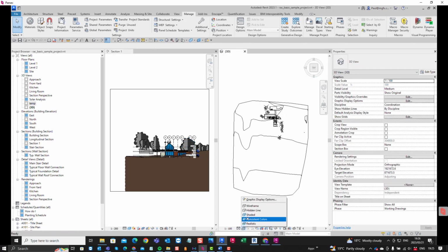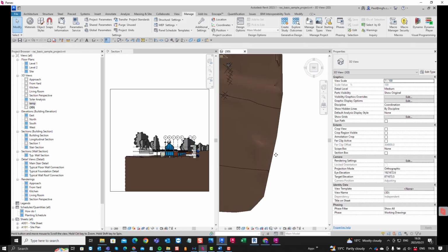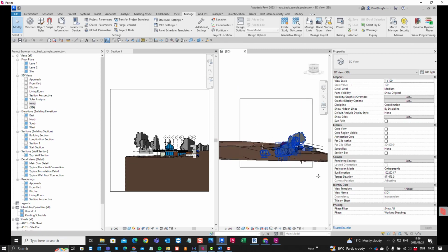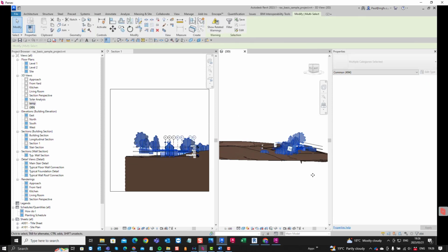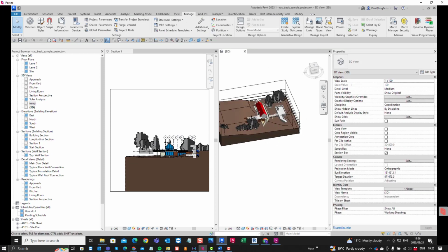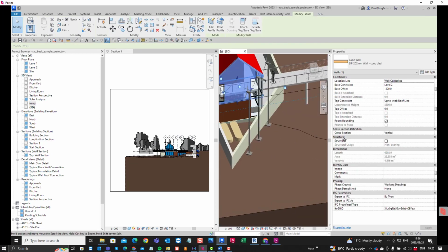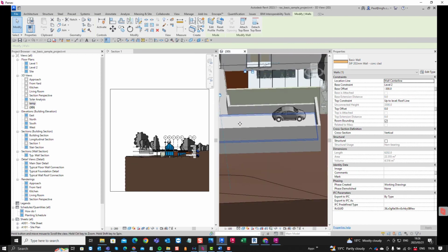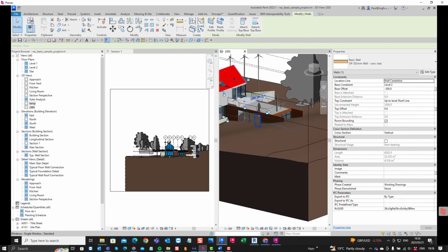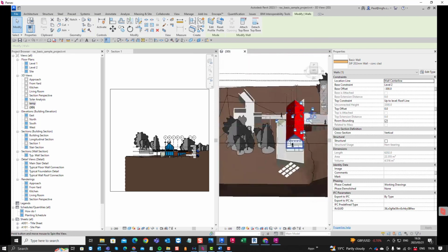And in the 3D view, let's go have a look at the orientation of that house. Again, to make this easier to work with, we can maybe just put a section box around there. Let's go X-ray. Choose an element on site to revolve around. Okay, so far so good. And we're going to do quite a bit of terraforming over there.